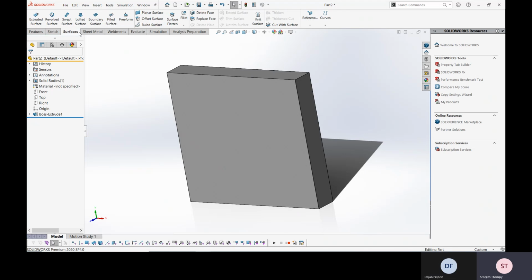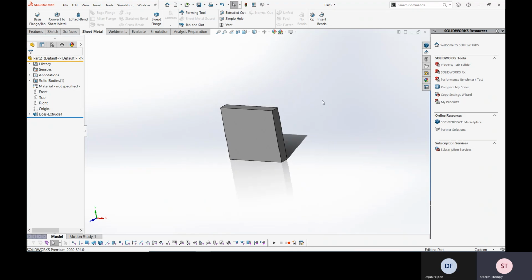And in the surface tab, similarly, you will have options to bring up surfaces and such for 3D modeling. And there are additional modules for sheet metal and all. If you're into sheet metal design, there are additional functionalities that help you in creating sheet metal parts. It is far easier than creating in a conventional way or doing it in 3D. The software automatically helps you in creating both the bent form as well as the flattened shape, and manufacturing drawings will be easy using the sheet metal module. So basically all the different tabs contain commands to do different operations.